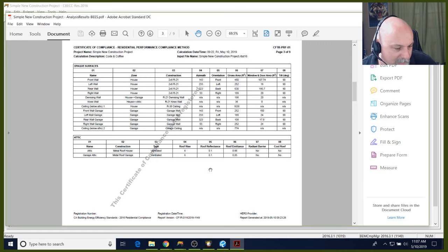So I have a comment in here. Lots of homeowners request to get rid of the gas furnace and change the entire house to electric. Yes, mini split is allowed. Mini splits can incur an energy penalty because of the way the Energy Commission classifies those. So it's going to look at it as if it's a minimum efficient air conditioner with ducts in the attic. So JC and Eli's dad says code only requires some kind of heating, not specifically a type. Yes, as long as you provide heating to the design specifications according to the building code, you're good.